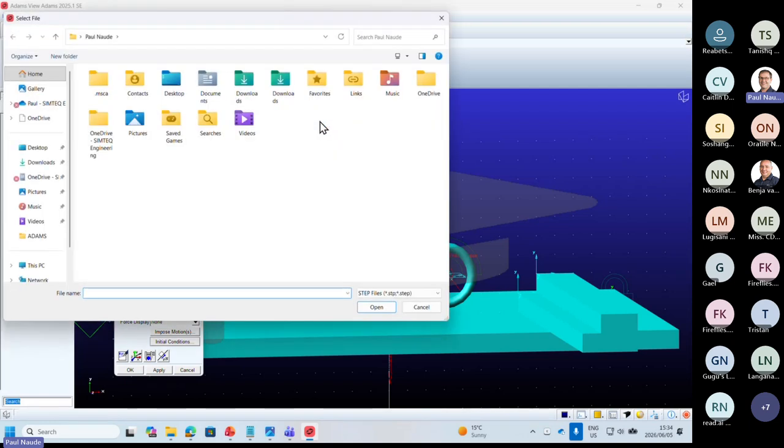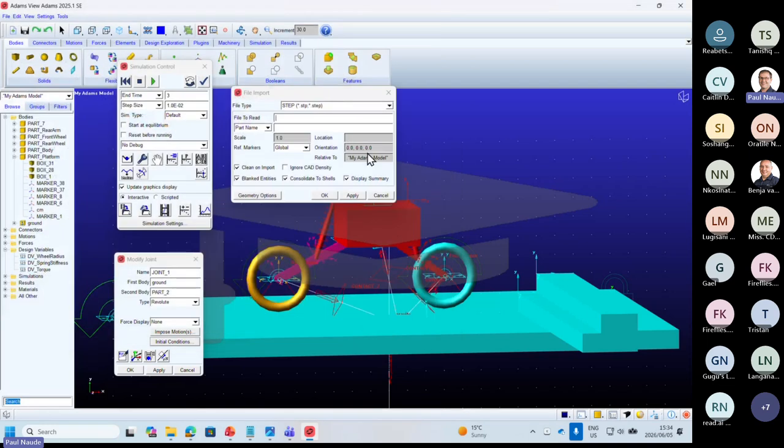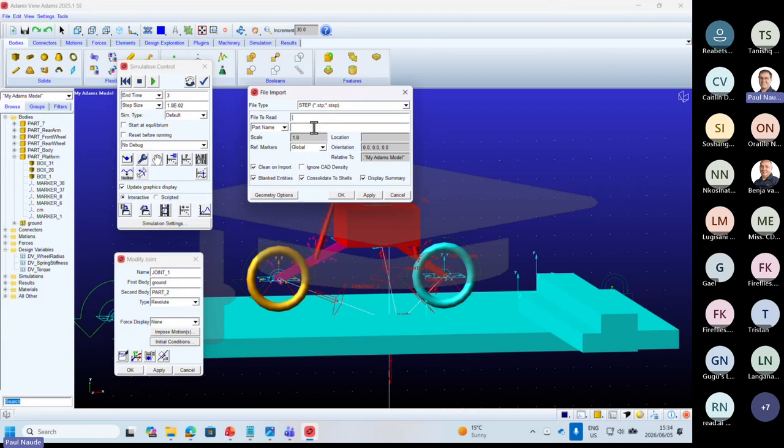You will then browse to your file, which I don't have an example ready now. And then you need to decide if that geometry represents a single part or multiple parts. If it is geometry for multiple parts, you need to import those into the model. What that then does is each piece of geometry that you import, a single part will be created from it.